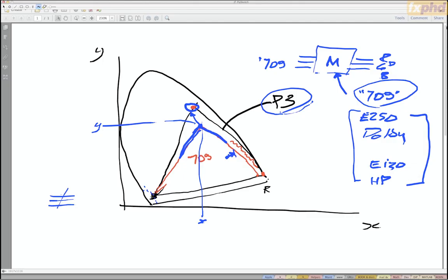Now let's switch gears and think about the other way around. If you take one of these displays and you set it to wide gamut position, so let's say you set it to P3 position, then you're basically instructing the display that you're expecting P3 data to be presented to the display. Now, these displays are typically not exactly P3 native, although they're pretty close. Any RGB LED illuminated display, which all of these are, has native primaries pretty close to P3.